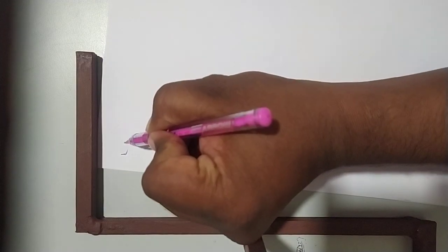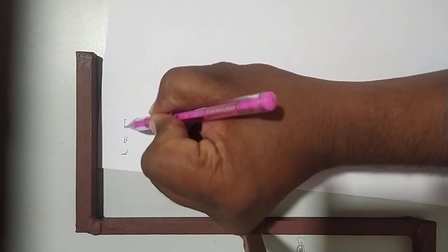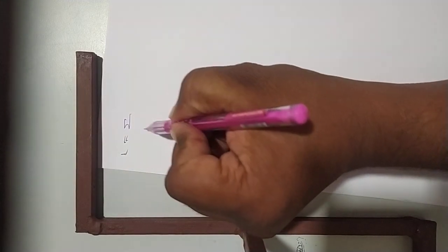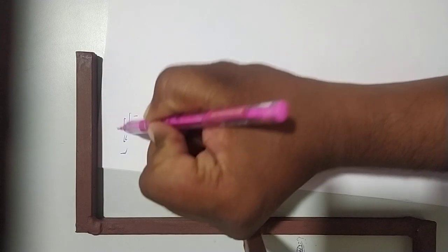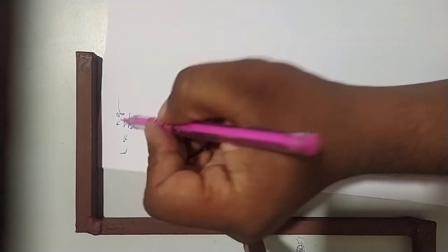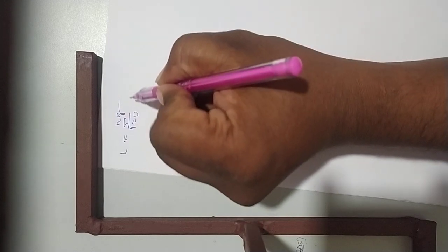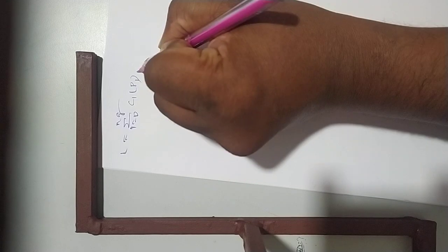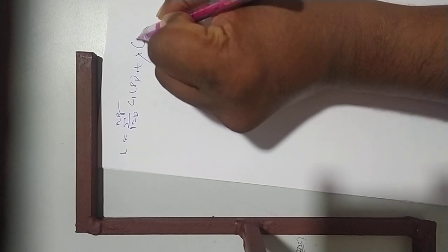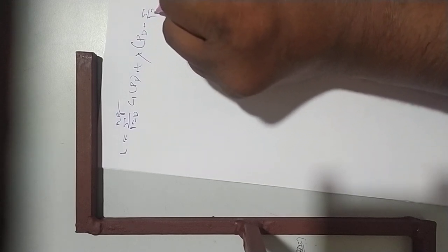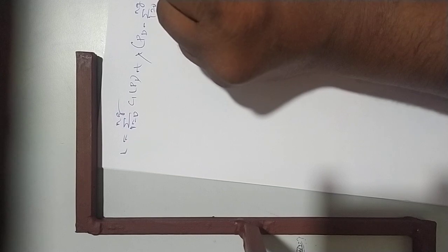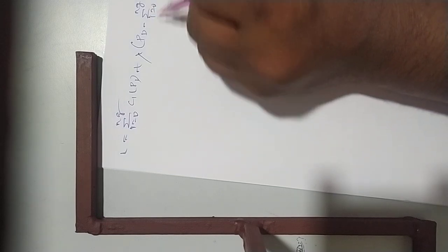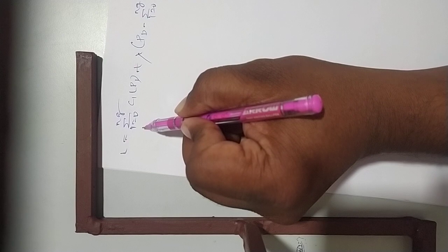Hence, L becomes the summation of F of P. We know that F of P is the summation for i equal to 1 to Ng of Ci Pi, plus lambda into G of P. What is G of P? It is PD minus the summation of 0 to Ng of Pi. This is the equality constraint and this is the total generation.